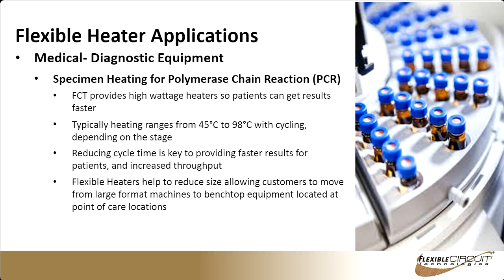If we look at diagnostic equipment in a little bit more detail, certainly PCR testing is one of the most common ones. It was common already, and then COVID came along, and in 2020 that market really blew up. So our flexible heaters allow you to have a high wattage heater that gets a patient a result quicker. Typically, these heaters range from an operating temp of 45 C to 98 C, depending on which stage it's at and which cycle it's in.